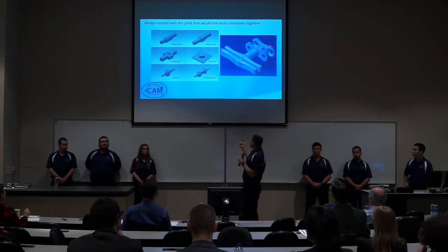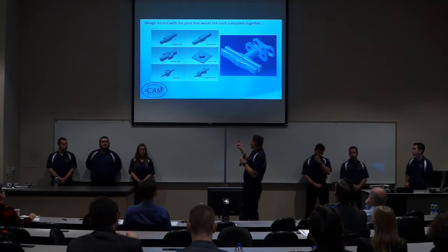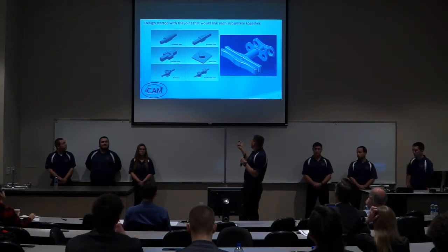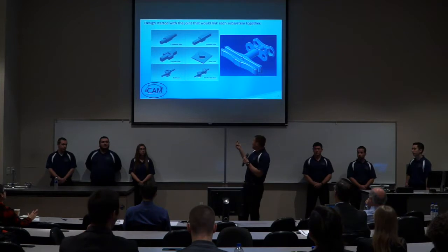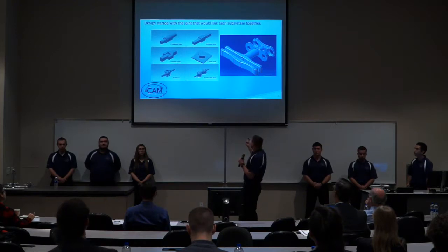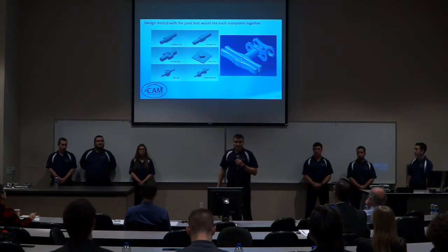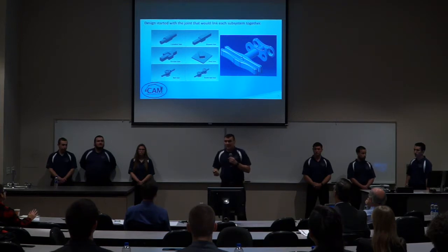Essentially how it works is that this outer plate is connected with this outer handle, and this inner handle is connected with this inner plate. Between these 2 handles is a spring, and when the handle is compressed, the handles will move together, thereby forcing the plates apart. These plates will force apart just enough to let a ball joint seated in this pocket rotate freely, but not enough to allow it to slip all the way through. So that is how that works, and then when the handle is released, the spring will force the plates together and lock the joint.